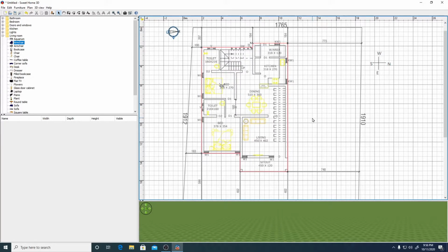So first what you need to do is finish up all the boundaries first. Okay, don't start drawing inside. Why are we doing this? Because we can easily draw using the create room tool, we can actually draw the entire area very easily. Otherwise, if there are open areas like this, drawing the floor will be slightly difficult. So the first thing I'm going to do is start drawing the walls.